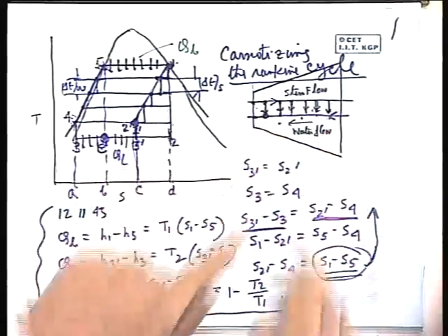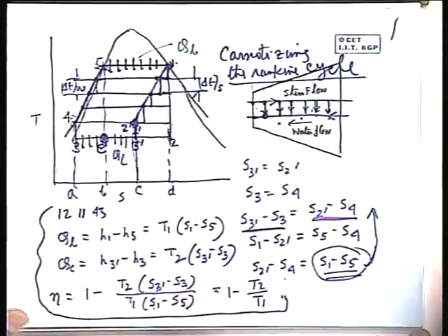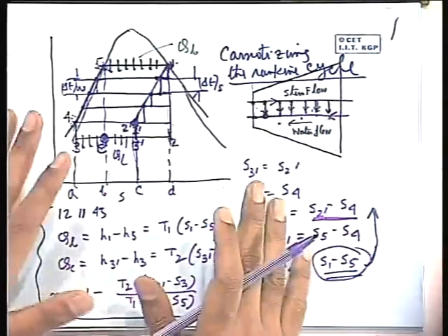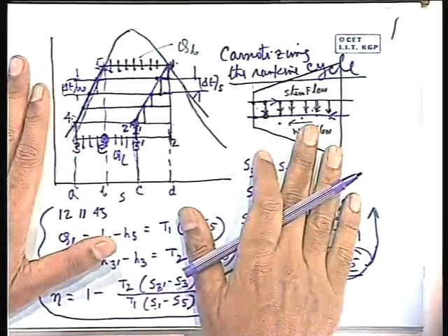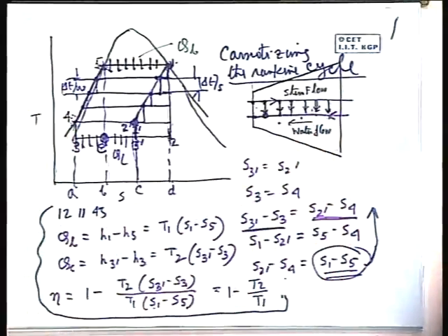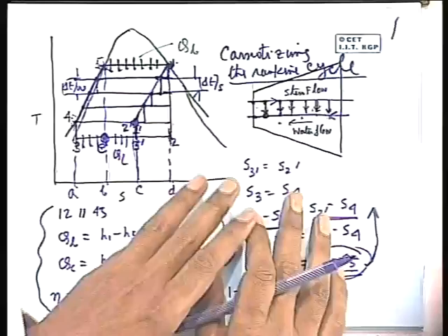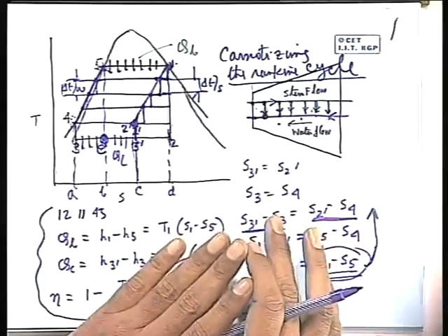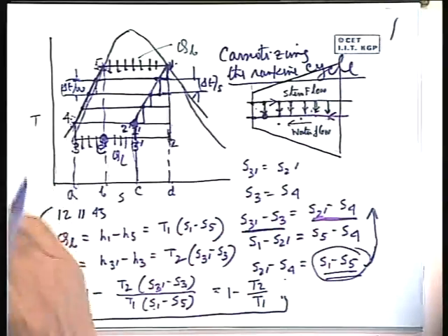So, this also cannot be implemented in practice. Okay? But this concept has been studied because it leads to a situation where we can implement it by some other means, this regenerative heating of the feed water, so that we gain in efficiency.